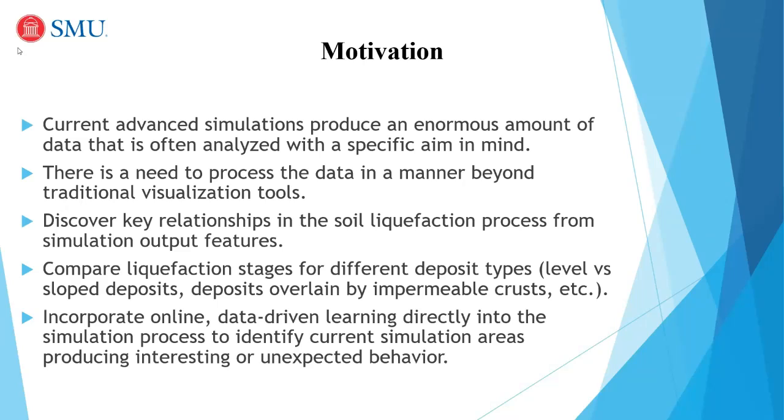So when we say advanced simulation, we're talking mainly about these types of new trends that can handle large strain effects on the behavior. These are typically needed for extreme conditions like earthquakes and flooding, where sometimes the mainstream tools that we have, such as finite element and finite difference techniques, implemented in very useful and popular software like FLAC and Plaxis, for example, just to name a few, may not perform very well and can involve a lot of approximations.